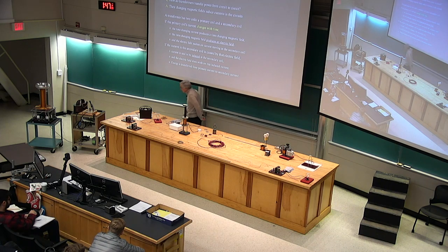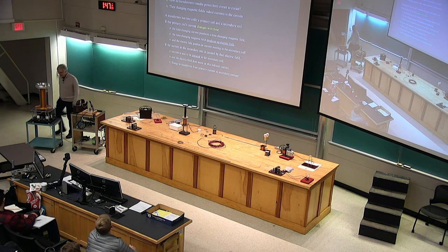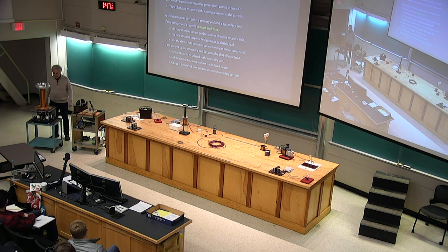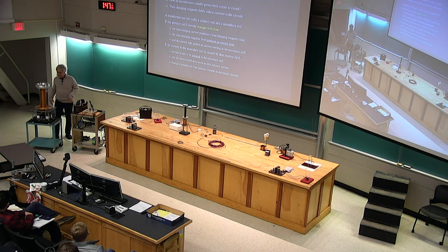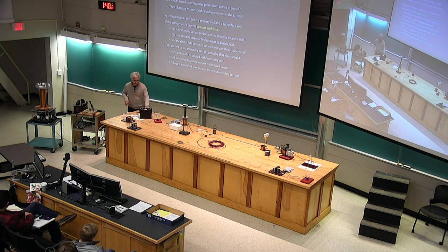And then go to the extreme case. Years ago, I built one of these guys. This is the professional version, much better. It's called a Tesla coil, and it is a transformer again. It's actually more than one transformer, but it's basically a transformer with a small number of turns in its primary, and you see them here, and lots of turns in its secondary, and it also starts at pretty high voltage. So it creates very high voltages. And it has no iron. It's an air core transformer. Therefore, it has to operate at much higher frequencies to be efficient. It's noisy, so be prepared.